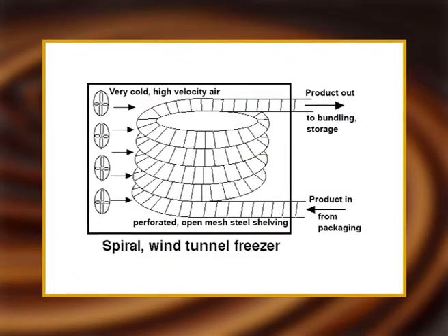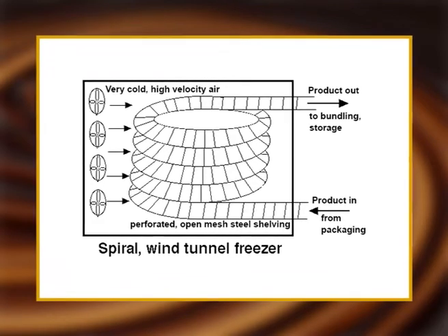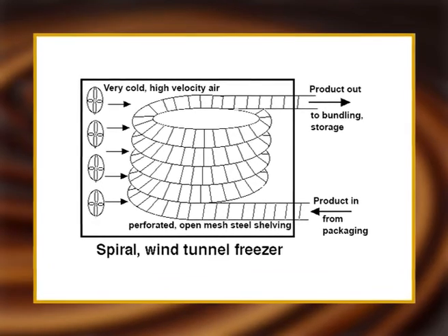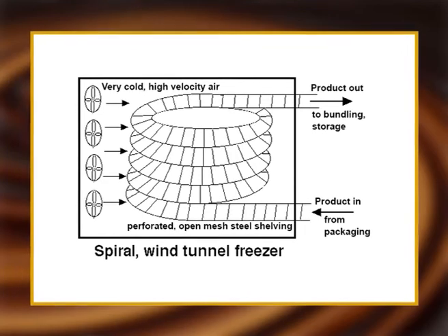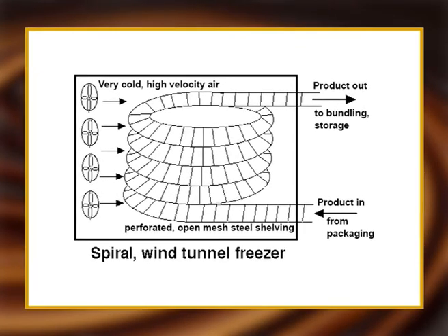Hardening involves static freezing of the packaged products in a blast freezer. Freezing rate must still be rapid, so freezing techniques involve low temperature with either enhanced convection or enhanced conduction. The rate of heat transfer in a freezing process is affected by the temperature difference, the surface area exposed, and the heat transfer coefficient. Thus, the factors affecting hardening are those affecting the rate of heat transfer.